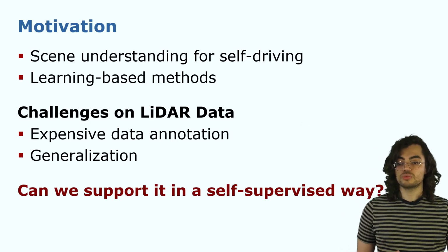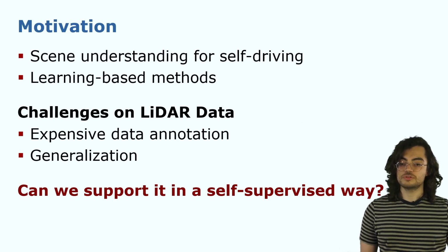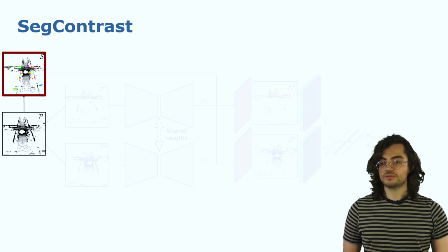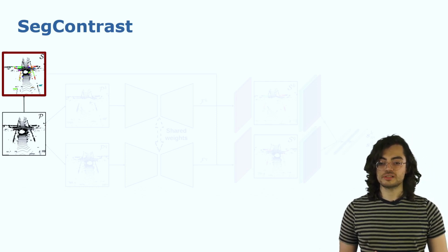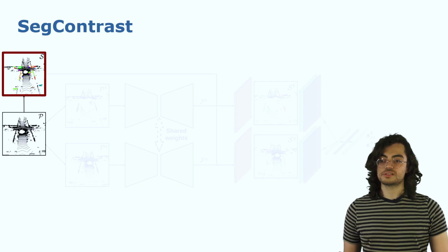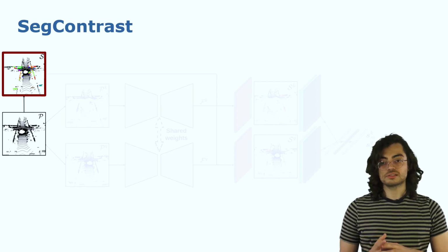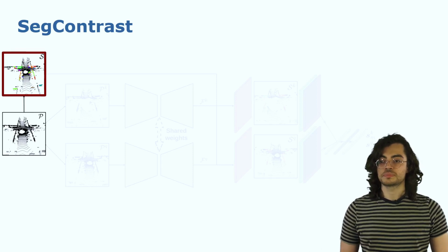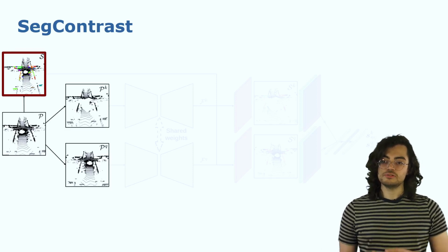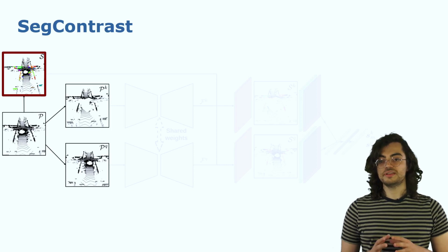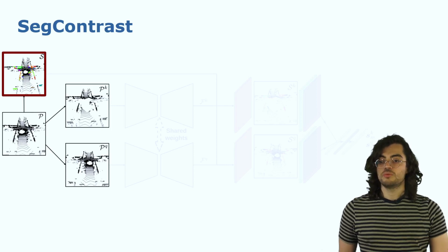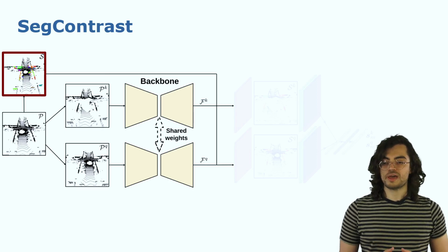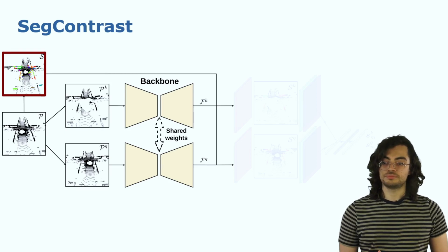In this work, we propose using contrastive learning for self-supervised pre-training on autonomous driving LiDAR data. Our method exploits the LiDAR point cloud's properties to partition a point cloud into segments by removing the ground plane and clustering the remaining points, achieving a coarse segmentation of the objects in the scene. Then, we apply a series of augmentations over the point cloud, generating a pair of augmented views. We compute pointwise features for both augmented point clouds using an encoder-decoder backbone in a Siamese network scheme.